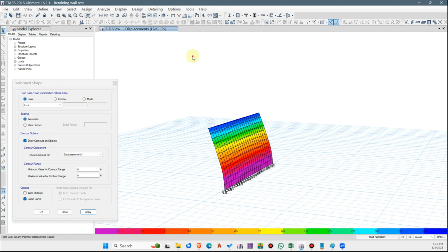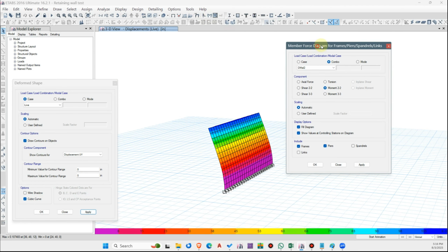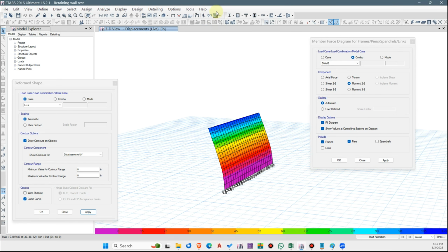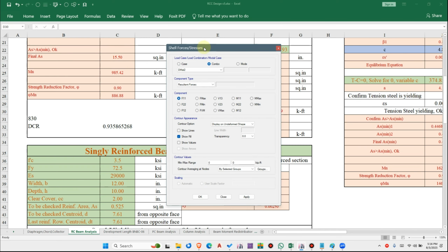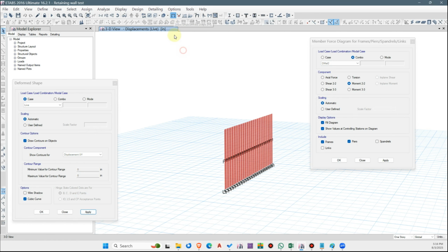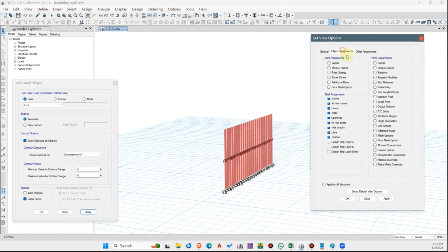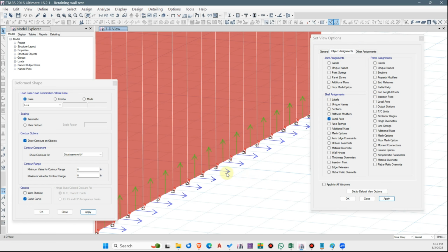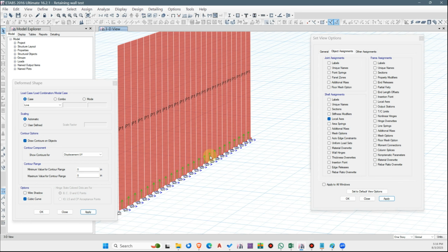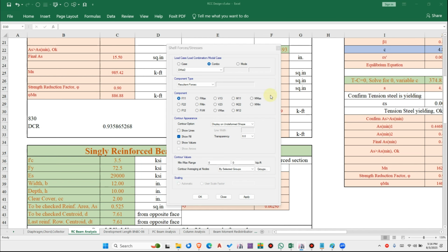And if we look at the bending moment, it can be checked in two different ways. One is under the shell forces. For example, D wall 2, we can check for the M11, M22. There are several ways of checking it. For example, if we switch on the local axis of shell, then we can understand which axis is 1 and which axis is 2. The red one is 1, which is along the wall, and the green one is 2. Basically, we'll be checking the M22 bending moment.